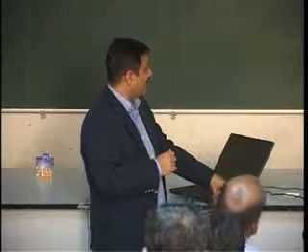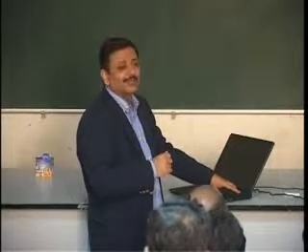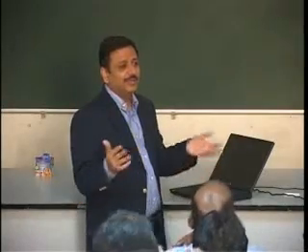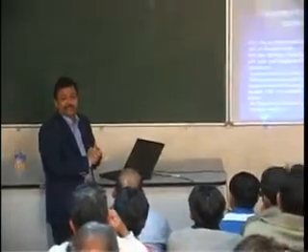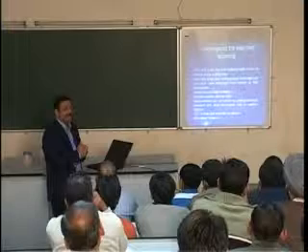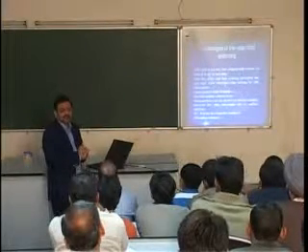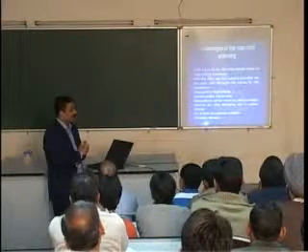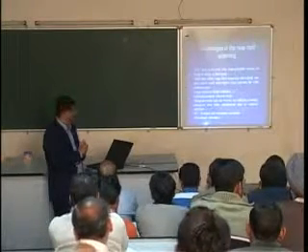Now, the measurement can be carried out without scheduled disruption. You can do this measurement within this room and you don't need to go outside, so it is all-weather. Sometimes the antenna you are making cannot withstand vibration or is not meant for weather conditions. Some materials are hygroscopic in nature, so you cannot use them in open space. So it is essential to do such measurement only in the near field.